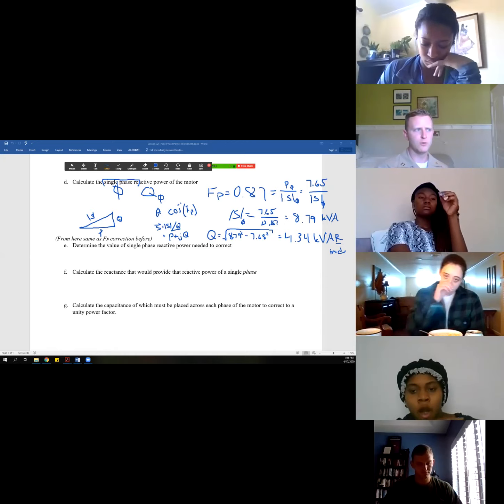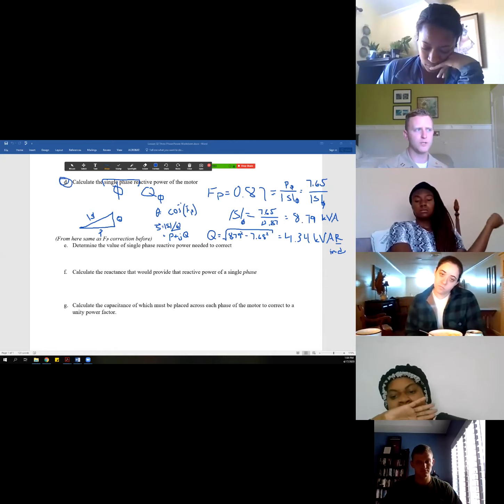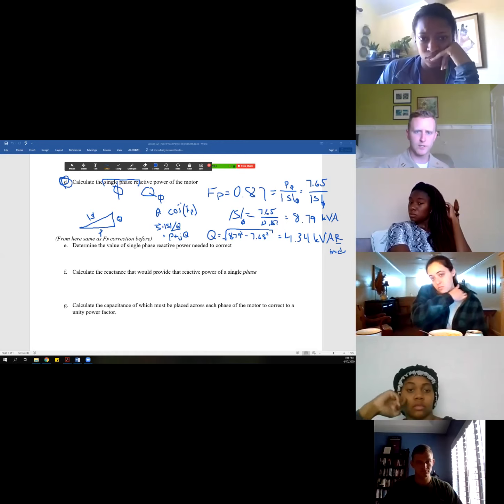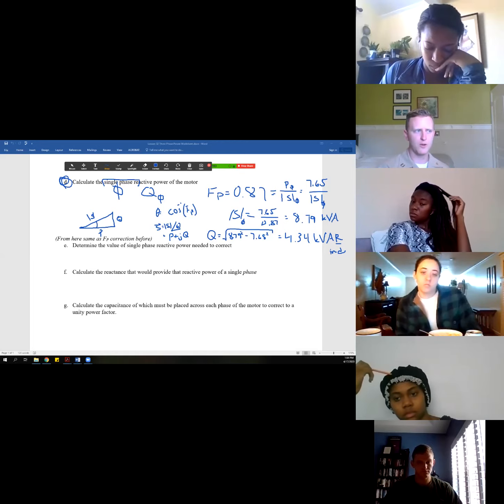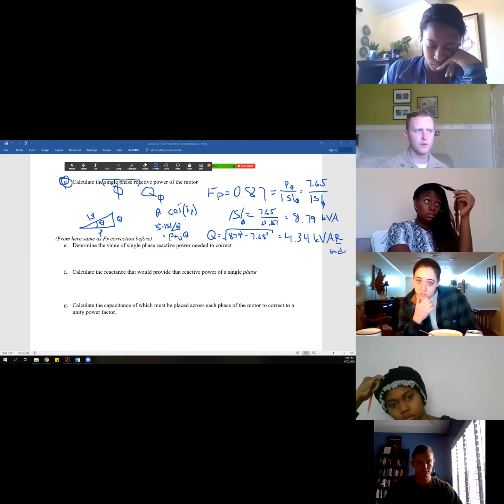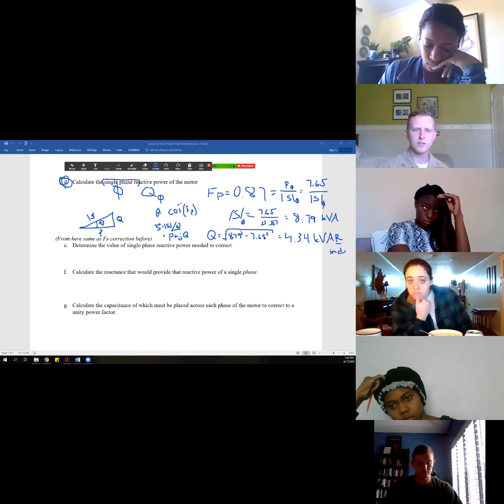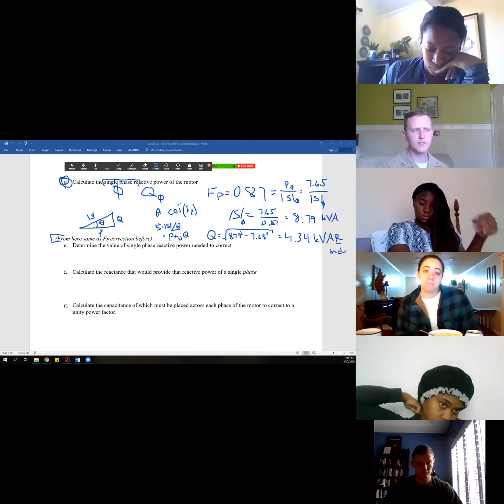But either way, in this part, part D, you decide how you want to get to Q. You know, there's multiple ways to do it. As long as you stick to what's true about the power triangle, there's theta, there's Q. Right, as long as you stick to the power triangle, you can't go wrong. And now from here, it's the same power factor correction as we had before. There's the same steps.